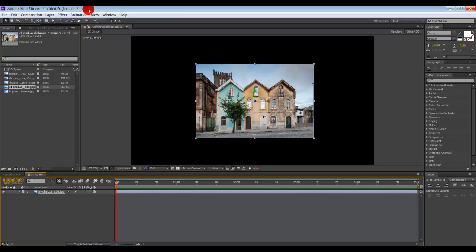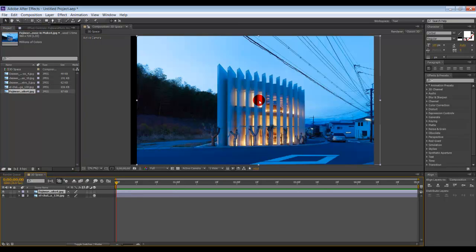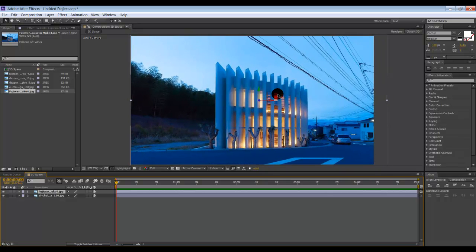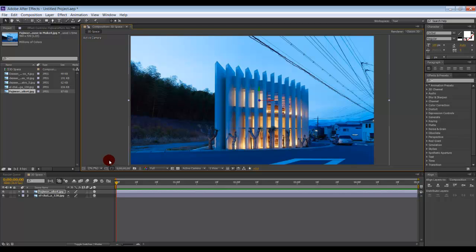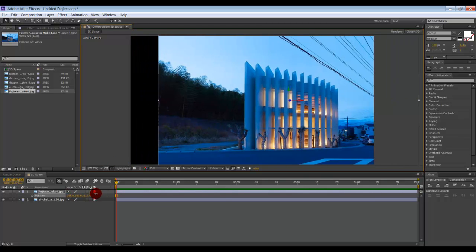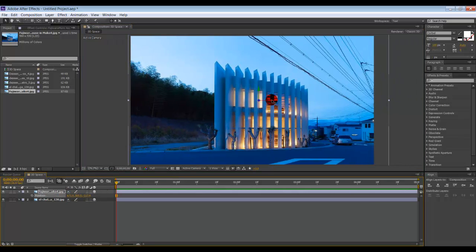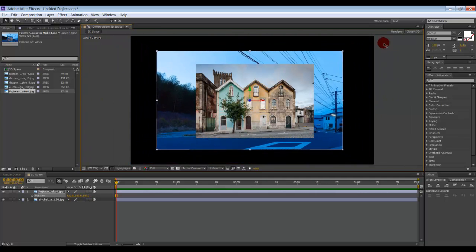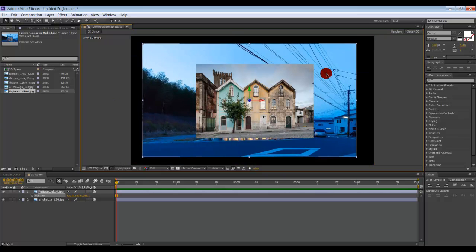To understand better how it works, let's drag one more photo in our preview area. We have to make sure to make it 3D. So we check the 3D button, and now we can move also in space our photo. We can either click P for position and then we move our photo, or if we hover on the 3 axes, we can drag our picture along the 3 different axes and Z as well. So now we are in 3D space.